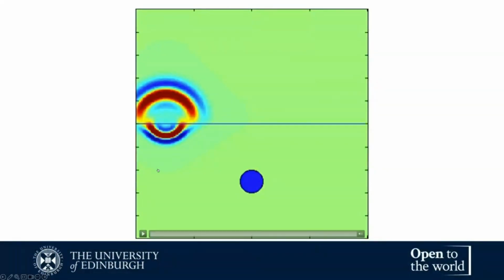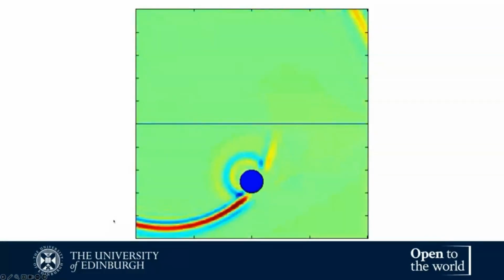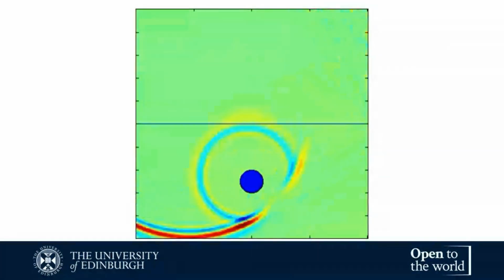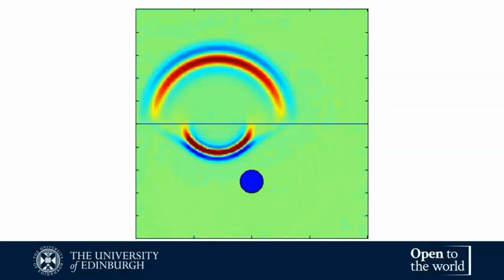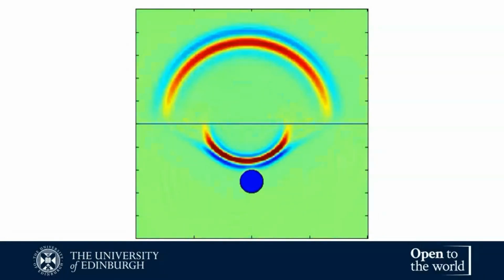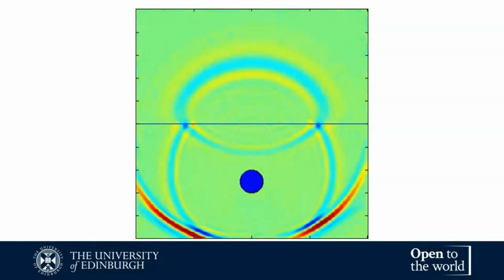Now, the easiest way to understand GPR is to take a very simple simulation. You have a source and a receiver very closely spaced, almost at the same spot, and you let the source send an electromagnetic pulse. The pulse will hit the object. The object will create another response, which will reach the surface and be recorded. And as you can see now in the video, this procedure is repeated as the system moves along a survey line.